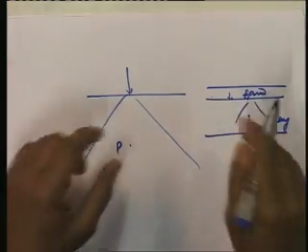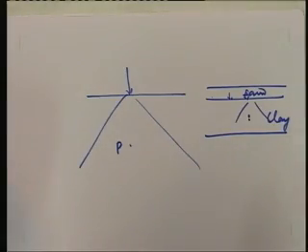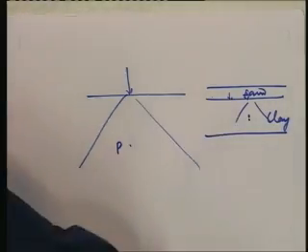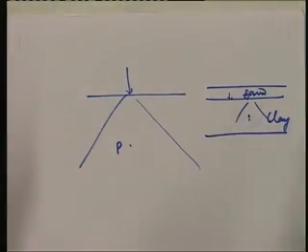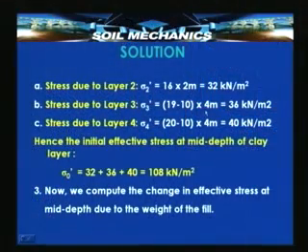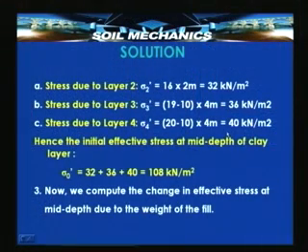This is valid because we are assuming a very large extent of loading as part of our overall assumption that the phenomenon of consolidation that we are considering is a one dimensional phenomenon. Okay. So, subject to this assumption, sigma 3 dash or even sigma 2 dash will merely be equal to the self weight of the material distributed uniformly without any reduction or dispersion within the clay layer.